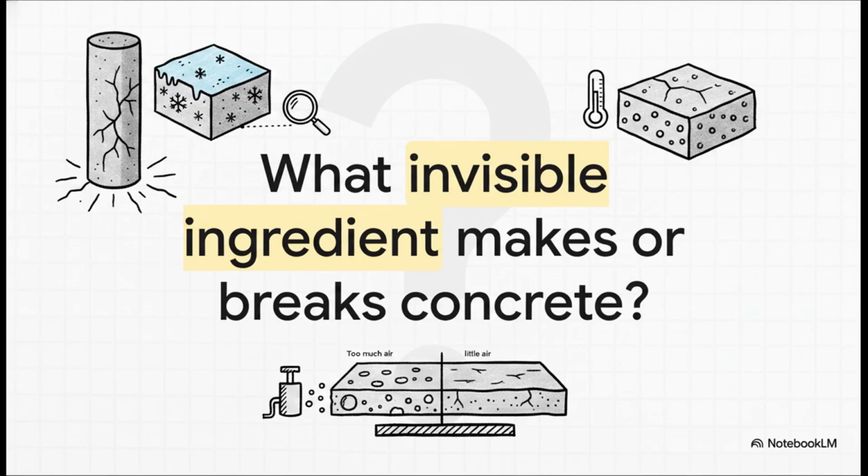But here's the catch. If you have too much air, the concrete loses its strength. Too little, and it cracks under environmental stress. This test is all about finding out exactly how much air is hiding inside that mix.